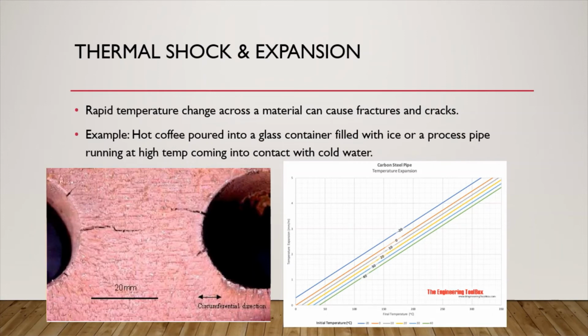If you are running very high temperatures in an intermittent service line, then it will go from ambient temperature to 300 or 800 degrees in a matter of minutes. For example, a pump out line to a flare. Running these type of lines, you'll need to keep in mind the operating conditions to avoid the thermal fatigue that could result on the material.